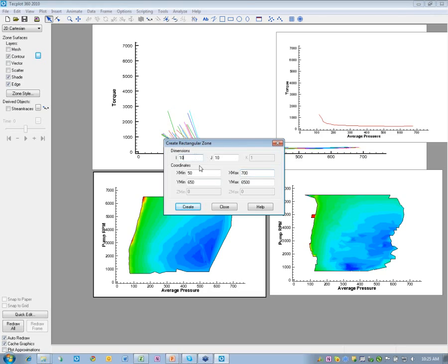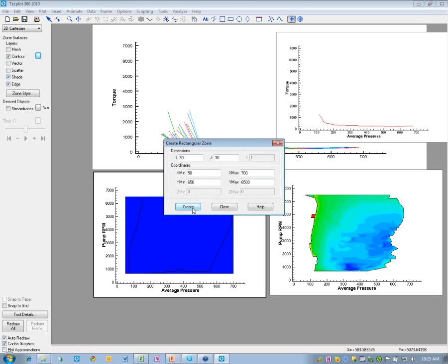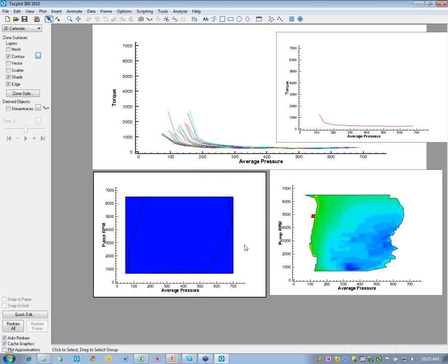Sure. Kriging is an interpolation technique that came out of geostatistics originally, and it is pretty effective. One thing it does is it goes through the actual data points when you're at the data point. It also gives you pretty good variation between them, in terms of a reasonable expectation of the variation. Now, one thing you mentioned, the linear.